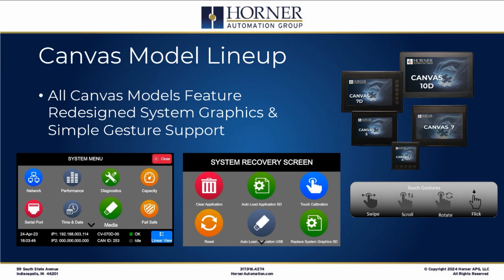Now, they're simple gestures. The Canvas is still primarily a resistive touchscreen-based hardware platform. Why resistive touchscreen and not capacitive touchscreen? Well, primarily because resistive touchscreen is still the most reliable in industrial applications and still the best option if you've got a glove-based operator. Now, we are exploring cap touch options in the future for Horner product lines, but Canvas does remain a resistive touchscreen-based unit. However, it does support simple gestures such as swipes and scrolls and rotates, for instance.